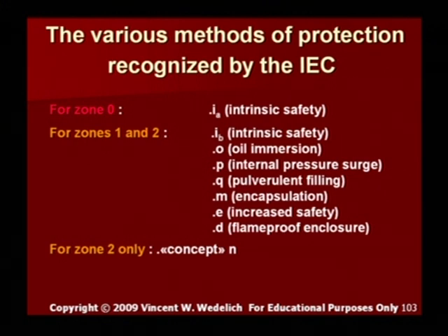So let's say if you had EXP, that means you've got an explosive environment that requires a P, or pressurized panel, and we'll talk about that in a minute. Then you have EXQ, EXM, EXE, or EXD, a flame-proof enclosure. And an EXD would be similar to a NEMA 7 box.